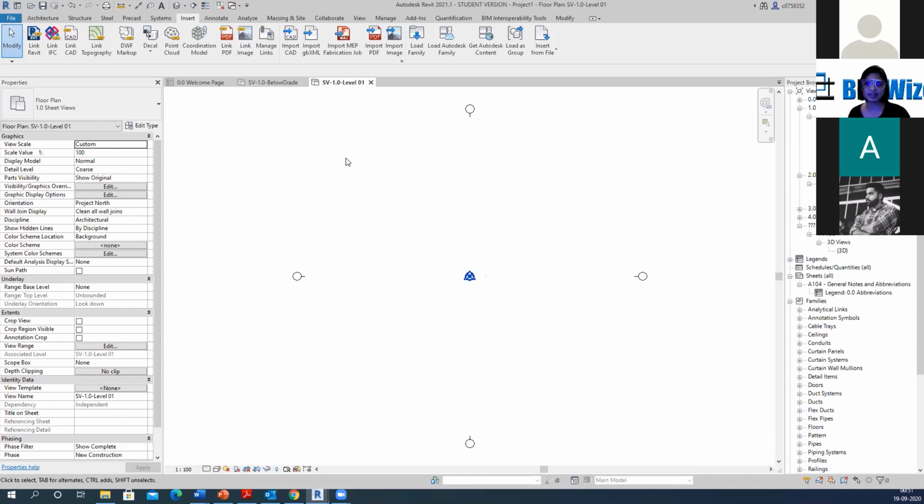I don't think you can get a student version of Revit 2019. You cannot get it. You will have to upgrade your 2019 AutoCAD file if you want to link it in. So install AutoCAD 2021, copy the file first, make a copy of it, upgrade it, and then link it in.